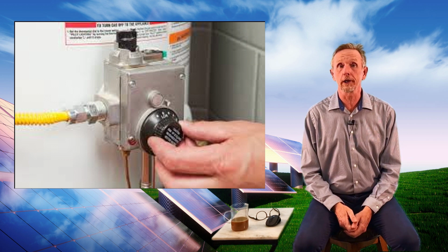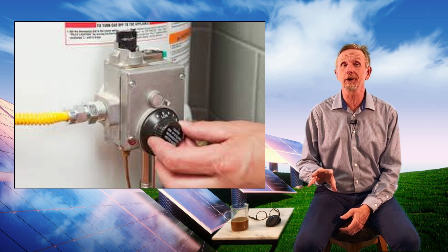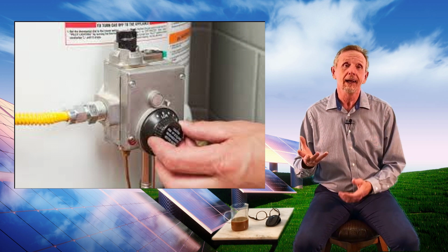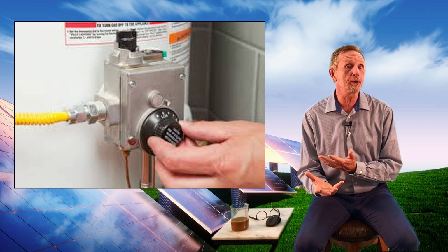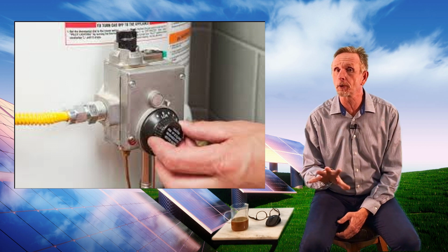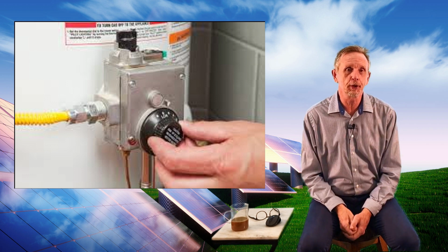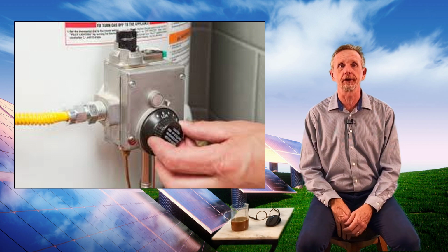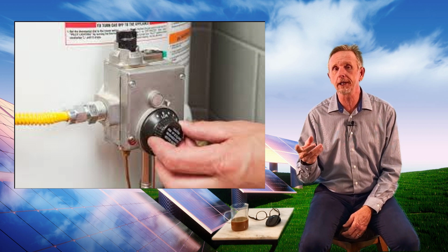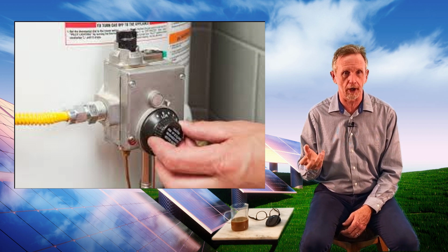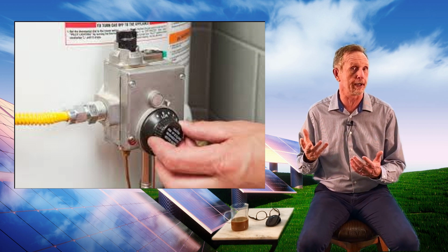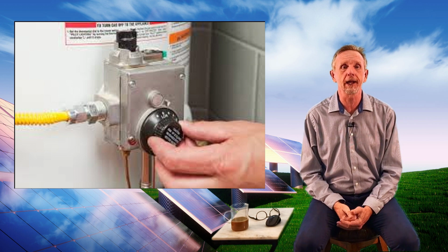Turn down the water heater. A lot of people have their water heater cranked up really too hot. You don't want it so hot it would burn you. Put it down to around 110 to 120. If you've got it around 130, 135, you're wasting money. It's not necessary. About 110 degrees is about as hot as you can stand on your hands. Beyond that, you start to get burned. Get the water heater down some.